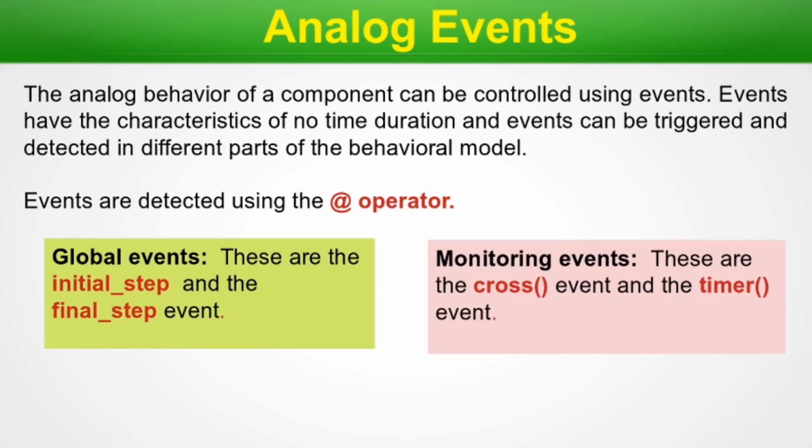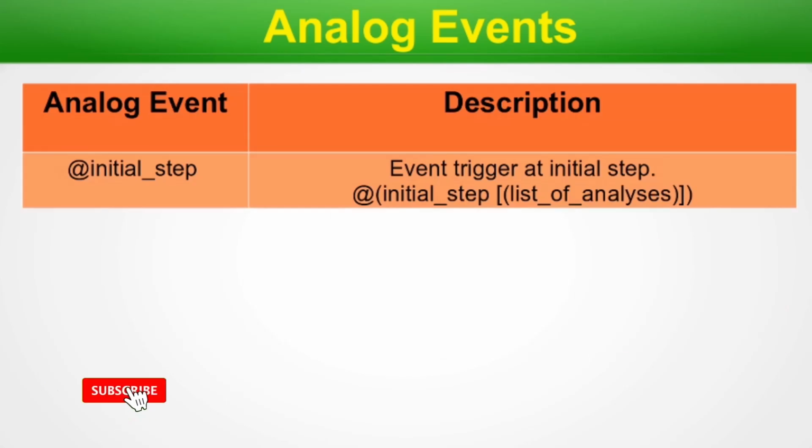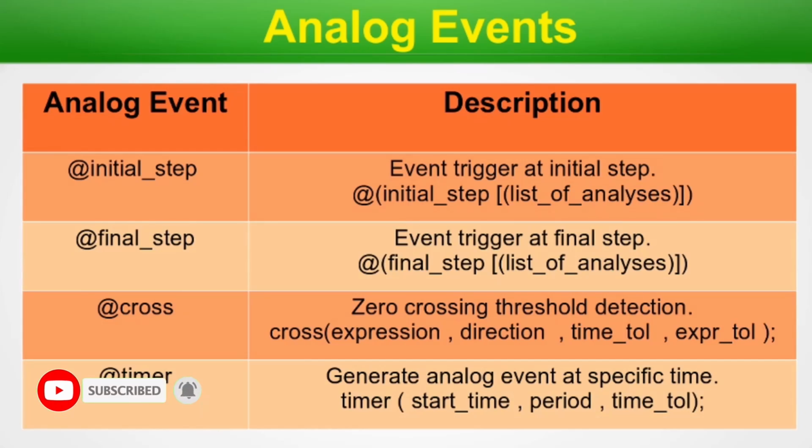Monitoring events. So these are the cross event and the timer event. Cross will handle the crossing of a signal and the timer will insert a particular time related stuff. So let's look into it. Here initial step, it is event triggering at the initial step. As I said, at the starting point of the simulation, initialization has to be done by this initial step. So here the syntax is @, then parenthesis initial step, and then will be the type of analysis.